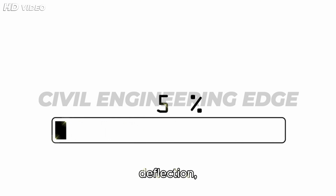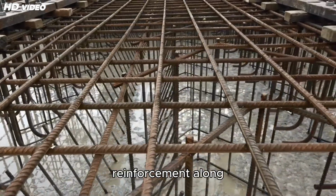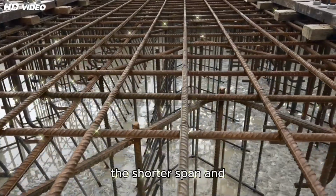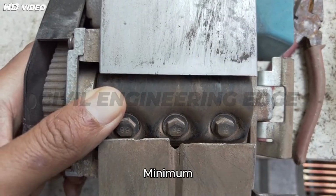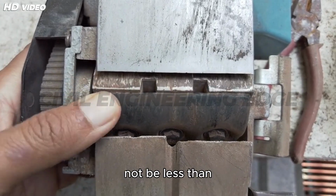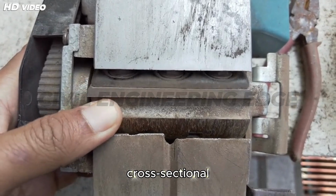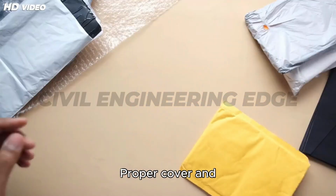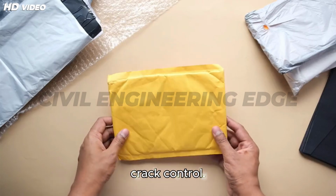6. Check for shear strength, deflection, and provide proper anchorage. 7. Place main reinforcement along the shorter span and distribution steel in the longer direction. Minimum reinforcement must not be less than 0.1% of the gross cross-sectional area for Fe 415 or 0.12% for Fe 500 steel. Proper cover and bar spacing ensure durability and crack control.